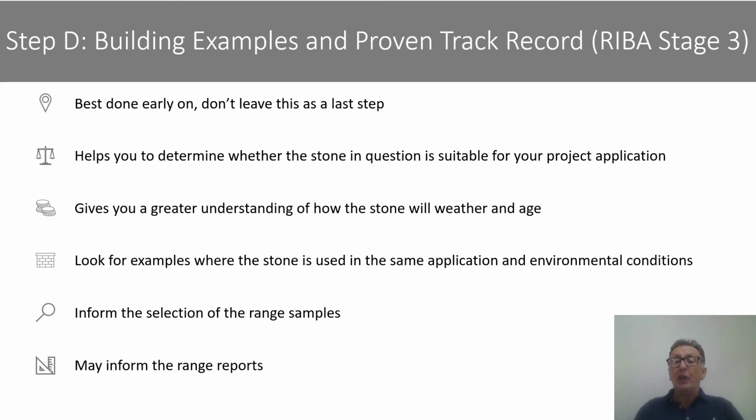But of course, you have to ensure that the material that you're looking at in the current production material is also similar in appearance and texture, etc., to the material that was being quarried that period of time ago, which could be 5, 10 or 20 years maybe, and materials will change and vary, so have that confidence and assurance wherever possible that the material you're looking at in the past application is similar to that you're examining in the current application.